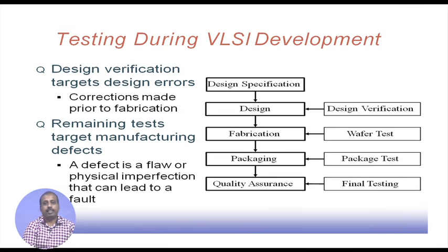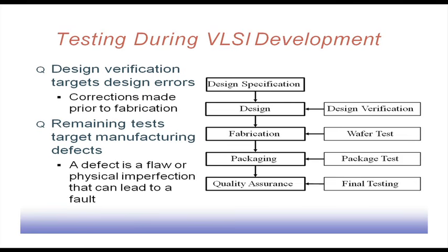Now, what is the guarantee that this design that I have got, consisting of flip flops and these gates, really has the behavior of the specification of the counter that I had? So, this is actually done by the verification process. Okay. So, if there is a design error, then this verification process will try to prove some properties of the specification onto this design, and if the design is incorrect, then those proofs will fail.